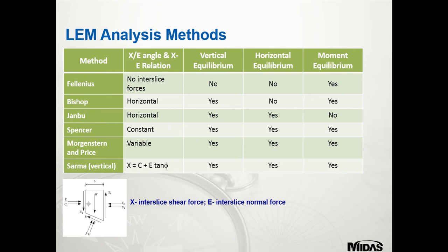Solving interslice forces is an indeterminate problem, hence several assumptions have to be made, and the table shows various assumptions made by each analysis method to solve the unknown forces acting on the slice. So just go down through all of them.